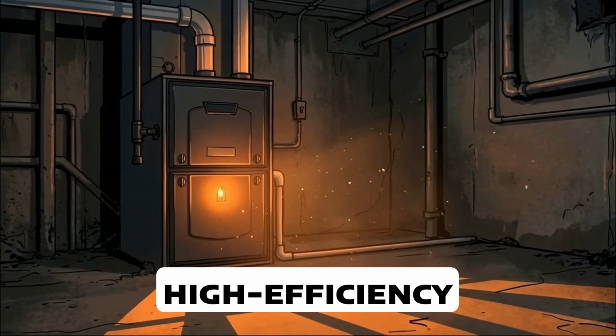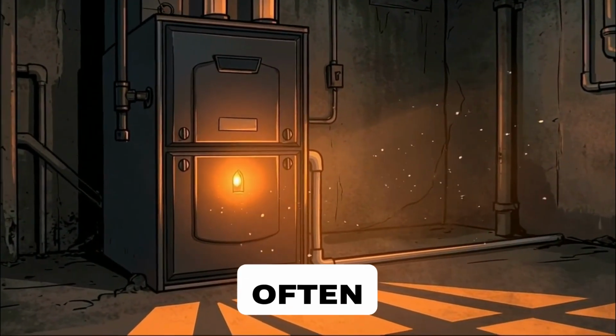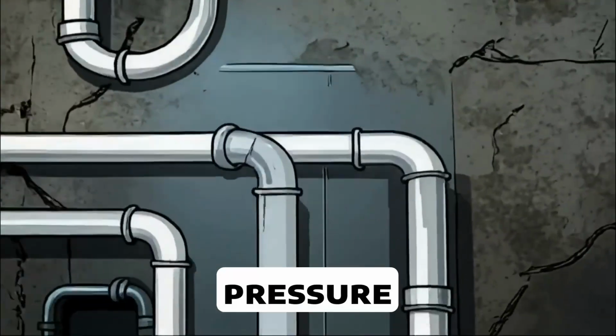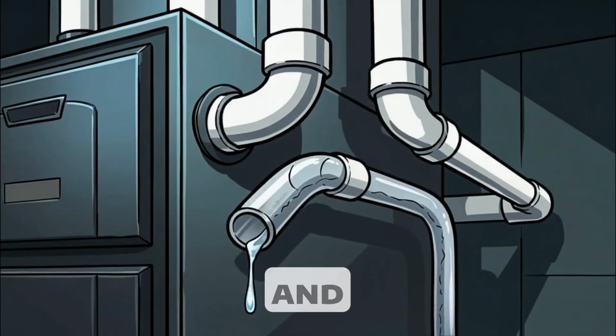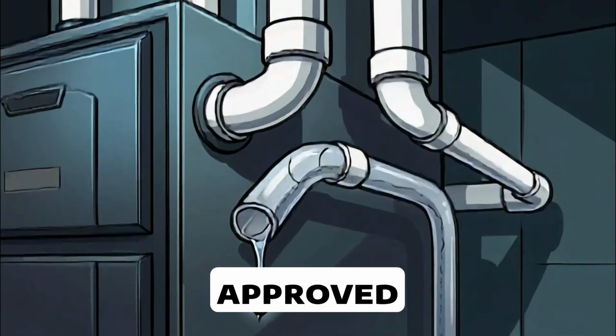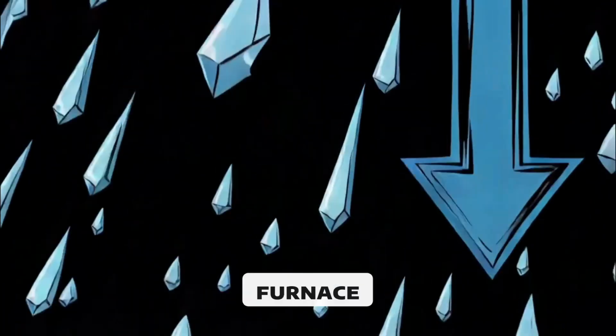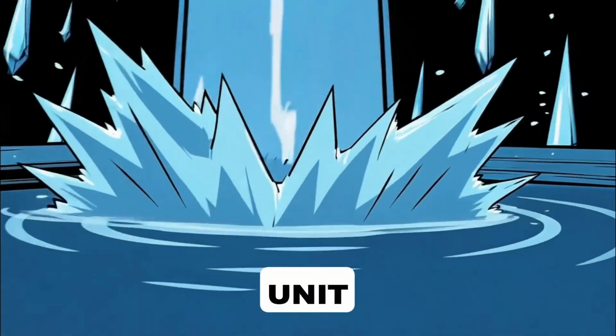Now, high-efficiency furnaces. These often include a secondary heat exchanger, sealed combustion, pressure switches, condensate drain, and PVC, or approved plastic venting where certified. If you see water draining from a furnace, it may be a condensing unit.